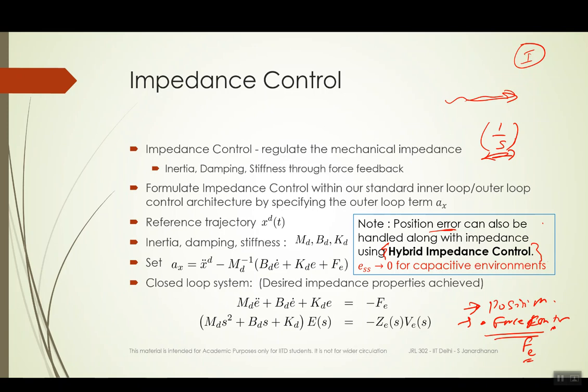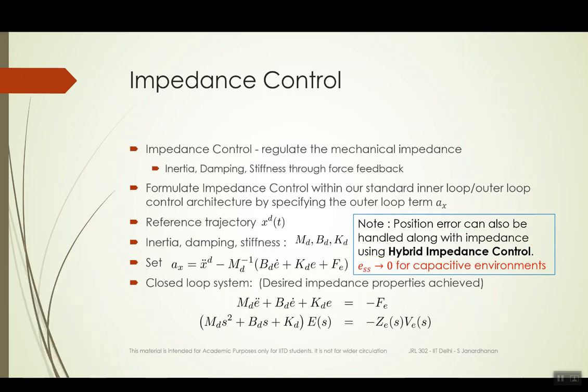Now if you go back and see which of the three impedance environments has an integrator in it, you see that the capacitive environment had an integrator in it. So if you have a capacitive environment, then you can assure that the steady state error can be made to go to 0 by choosing an appropriate impedance based control.